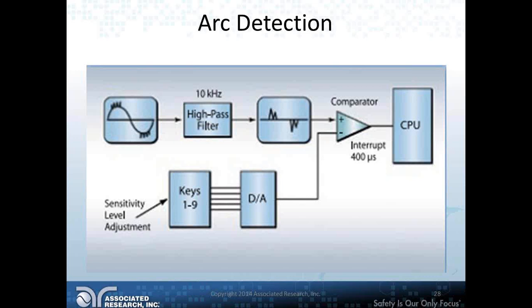But the arc failure does not mean a high-pot failure. These are two different things, two different failures, two different phenomena. High-pot failure usually refers to a breakdown or excessive leakage current flowing, whereas arc detection is a momentary condition. So it should not be confused.